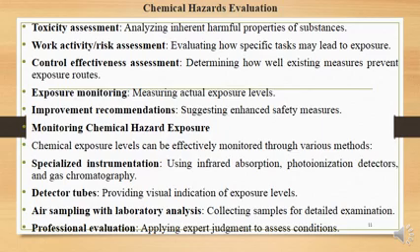We have specialized instrumentation using infrared absorption, photoionization detectors and gas chromatography. Detector tools provide visual indication of exposure levels, air sampling with laboratory analysis, and professional evaluation.